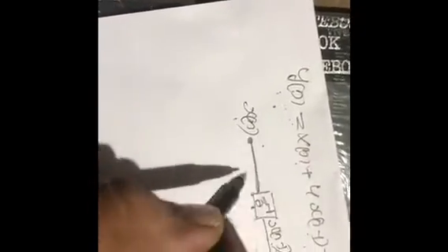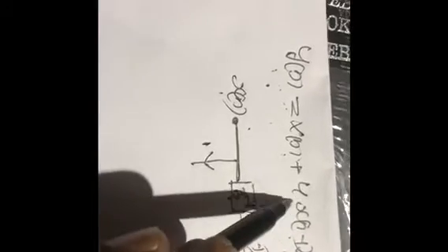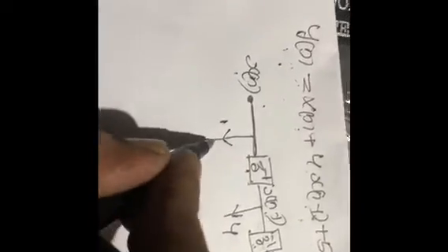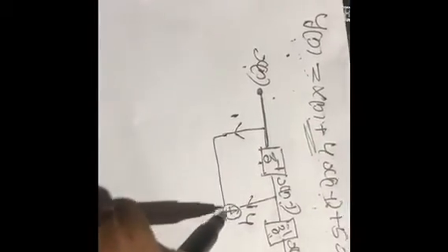Then in the first sequence we know that there is x(n) with a multiplier or coefficient that is 1. In the second sequence, there is a coefficient. That coefficient is 4. So I wrote down 4 here. And these two are summed up, and I use an adder here.